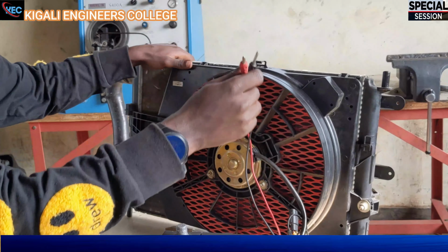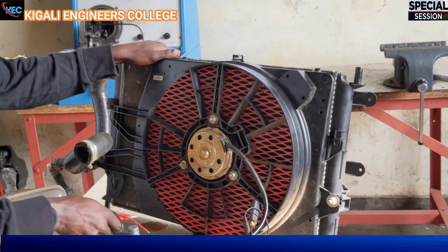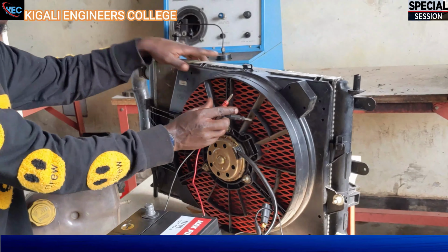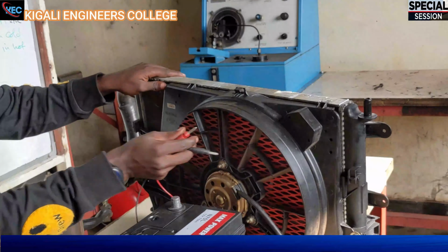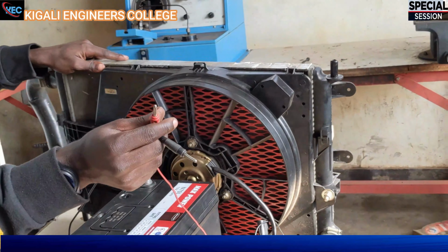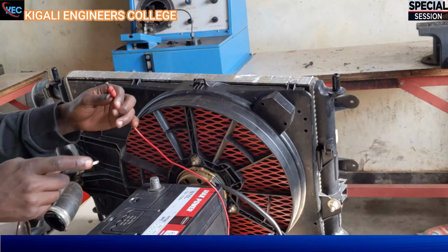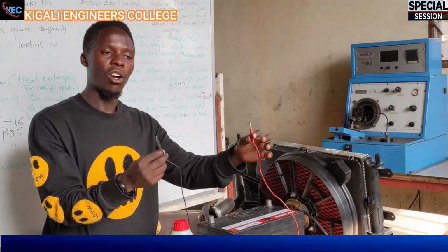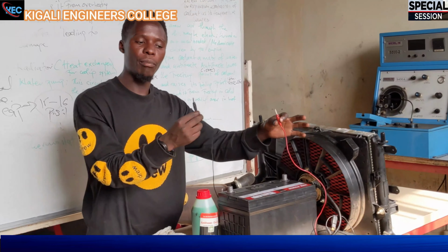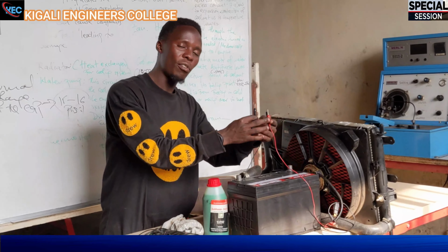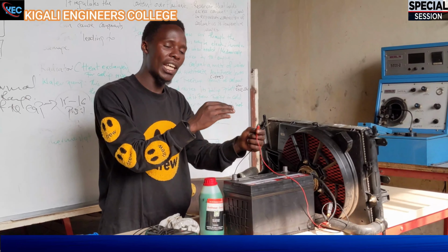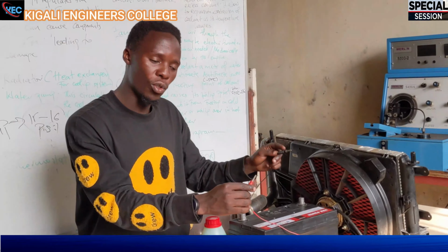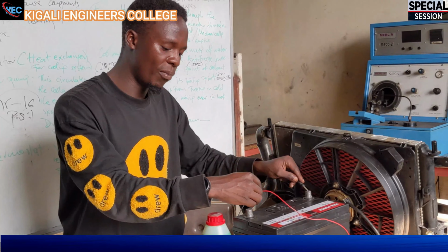So, what do we do then? Let's do it this way. Here we have a ready adapter, which is not easy to adapt here and make it stand, but we shall try our best. So, I have red and black here. Always red is positive and black is negative. First of all, we have to see how they connect so we can get the correct direction of the motor. So we put this black onto the negative pin and this red onto the positive pin.